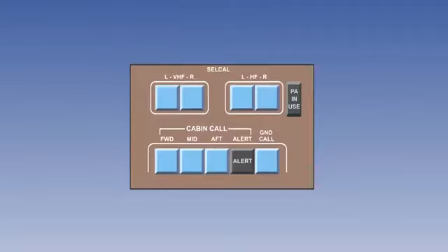So, some equipment is fitted with a selective calling system called SELCAL. This is a 4-letter code system which enables air traffic control to alert a pilot that ATC wish to speak to him. This avoids the pilot having to monitor his frequency continuously.